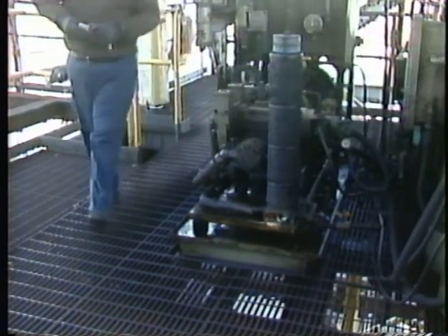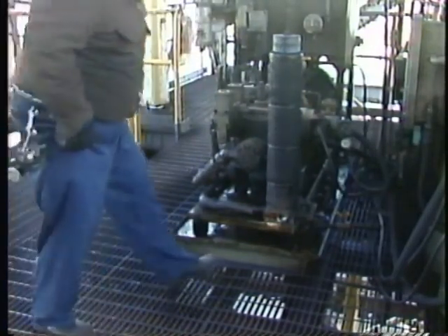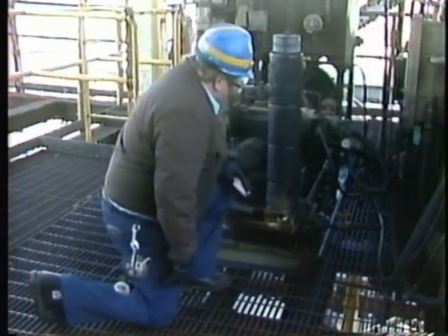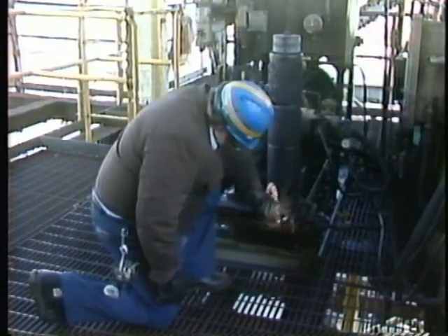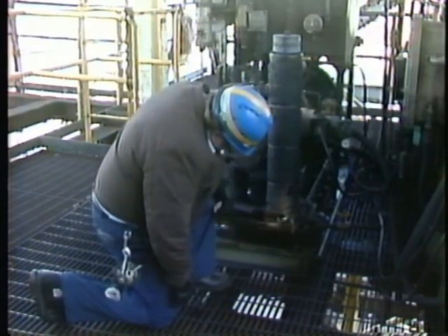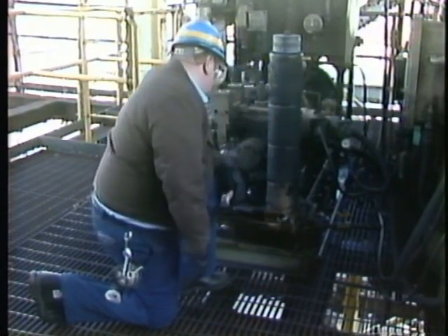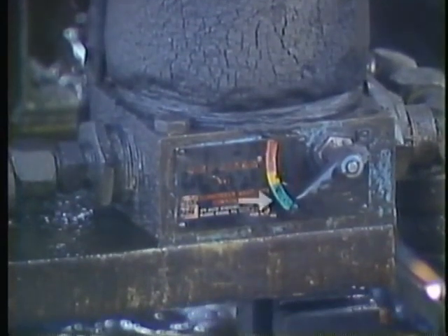Another component to check on a hydraulic system is the filter or strainer. Filters or strainers have to be checked to see if there are buildups of dirt and other contaminants, which can restrict the flow of fluid. Some filters and strainers can be cleaned, while others use replaceable cartridges. In some cases, they're replaced on a scheduled basis. This filter has an indicator that shows an operator when it needs replacing.